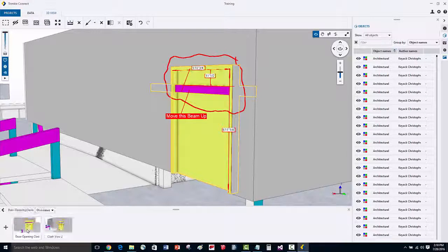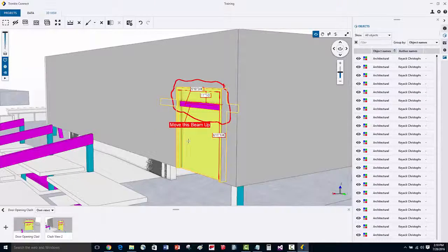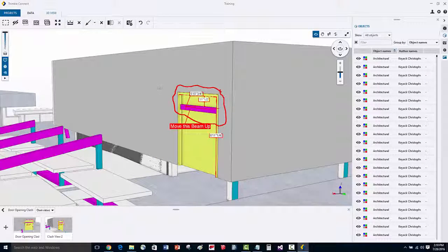All right, so let's go ahead and go to the views inside of that group. And then what we can do is we're going to update the view. So let's go ahead and zoom out a little bit more, and it will clear the selection of objects. And maybe I'll even delete one of these dimensions. Now what I can do is I can right click on this and say Update View.